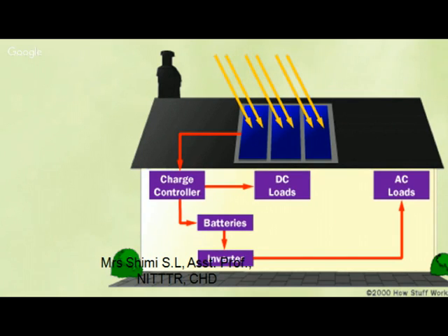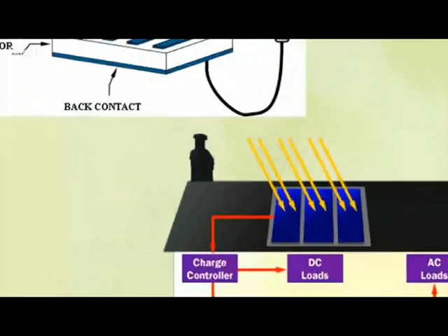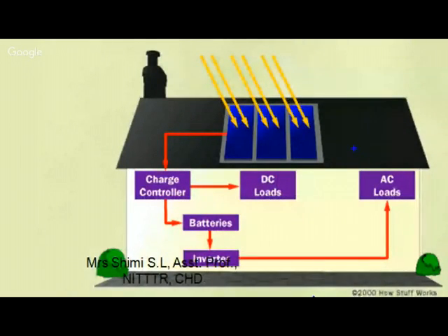So here in this case, let us take the PV panel to be around 37 watts. If this is 37 watts and we are saying around 17 volts is the output voltage, and our battery is around 12 volts, so here in this case we require which converter? Buck. We require a buck converter here in this case.